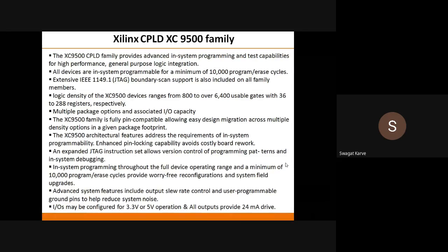When Altera developed the first CPLD, that is the 5000 series, and then went for the Altera Max 7000 series, obviously some advancement was there. When they went for the Altera Max 9000 series, along with the basic structure of the 7000 and 5000, there were again some additional features. Likewise, the higher end series have been developed. But the thing to remember is that the basic architecture won't change. Basic architecture is the same for every case and for every CPLD.